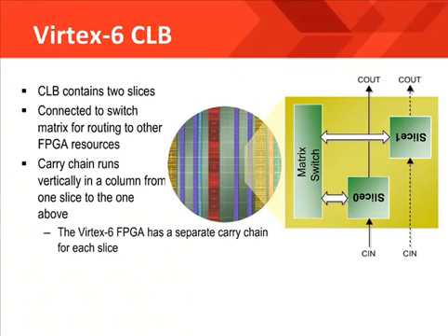Determining which density is right for your application often requires you to at least synthesize your design before choosing an appropriate density of FPGA. Only with some experience can you properly estimate how many slice resources will be necessary for your design without at least synthesizing the design first.